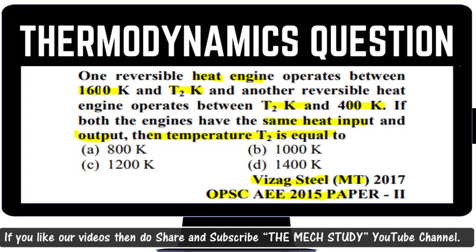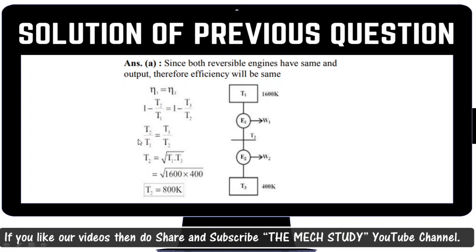Remember that they have given a temperature of 1600 for the first engine with T2, and another reversible heat engine operating between T2 and 400, and you need to calculate T2. You just need to remember the same formula which I explained in the previous case: T2 equals the square root of T1 into T3. If you put T1 and T3 over here, 1600 and 400, you will get T2 as 800.